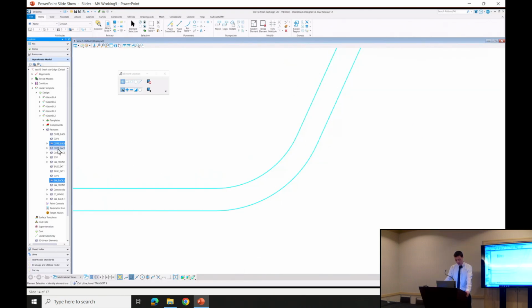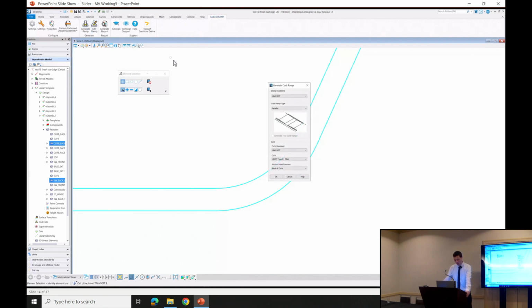And these aspects of the intersection infrastructure are ultimately the backbone information used to design the curb ramp. For example, like I mentioned before, when I was designing curb ramps in California, we actually used a flow line, which is in front of the back of the curb, and that was used to calculate corresponding points through rise over run.